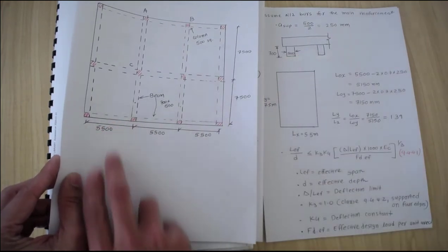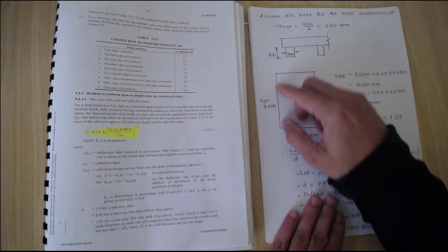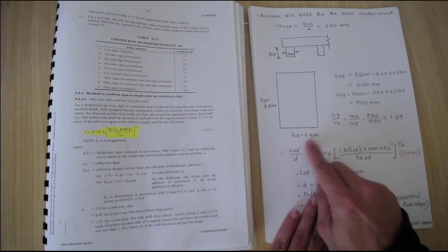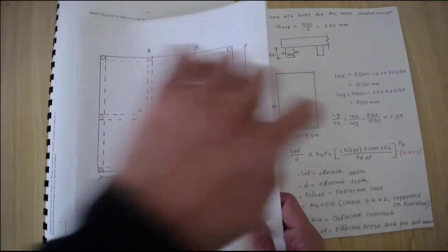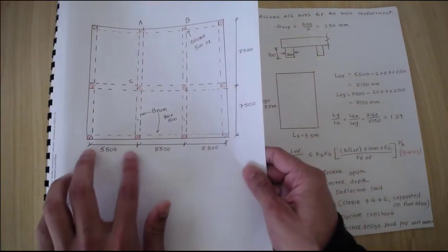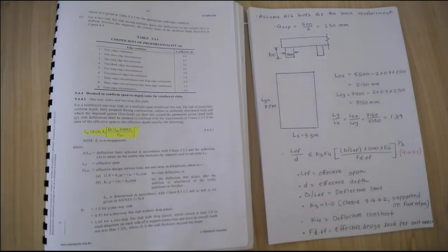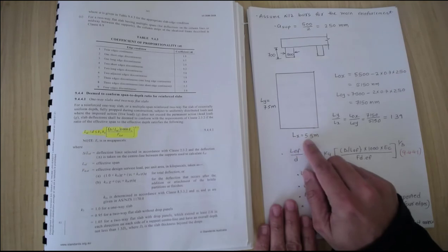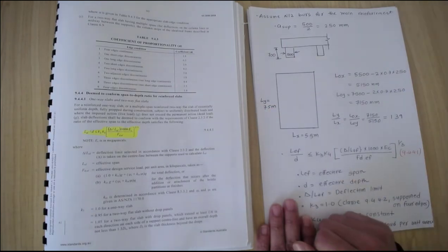I just draw these cross sections here. So it's 250 millimeters. Now I already explained these definitions, where the shorter length you denote as 5.5 meters. So I redraw this corner slab that we are working on. 5.5 meters is coming from here, and 7.5 meters is coming from here. In this one we can identify 5.5 is the short length, so it's LX, and LY is the longer length, so it's let's say 7.5 meters.